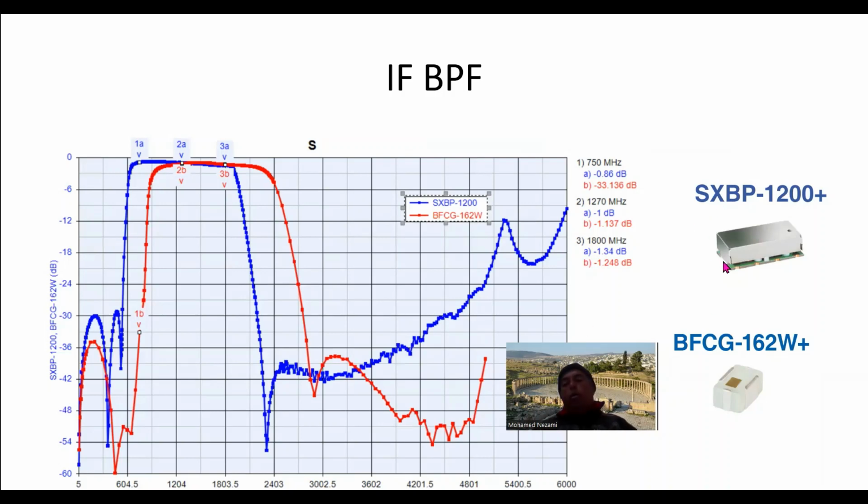So we're going to go into one of these devices here. Either this or this will do. As you can see, as long as it passes somewhere between 900 to like 2200, either one of these devices will work. These are low cost. This is way lower cost than this one. I think this surface mount filter module is about $30 each. This one here is like $5 or something. So you can cascade as many of these stages as possible. And of course, you get about a dB loss throughout the filter.